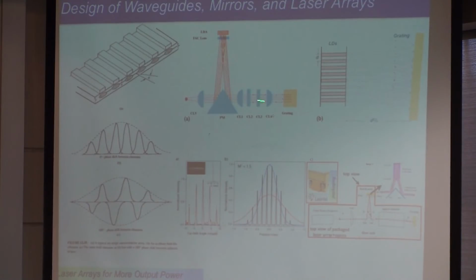And you take the light out, and you very cleverly take the light out from one, and you do mirrors and gratings and reflect it back, and you feed in the light from one to the other and so on. So you combine them such that they end up locking completely their phase. All the phases of each individual laser start locking into the other. And then by combining many of these laser diode separate emissions, you can get one center frequency, one laser with power roughly equal to the sum of all the outputs. It's not exactly, you always lose some in this process, but you can combine them.